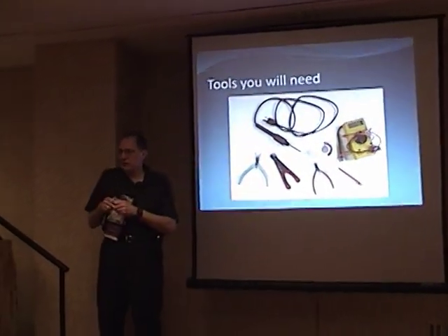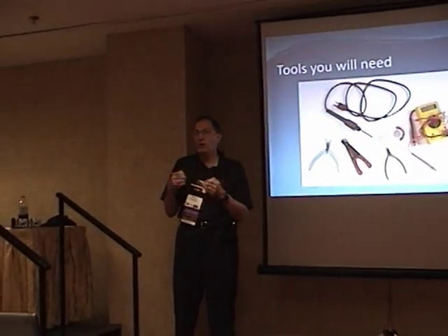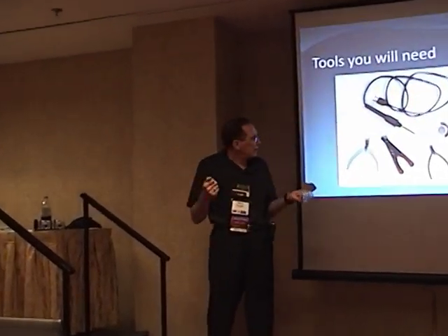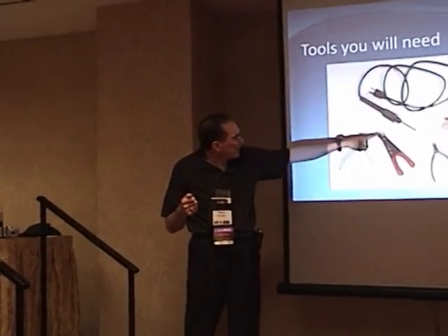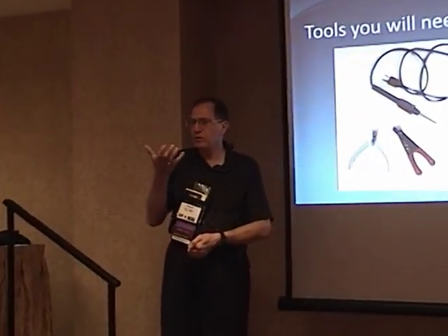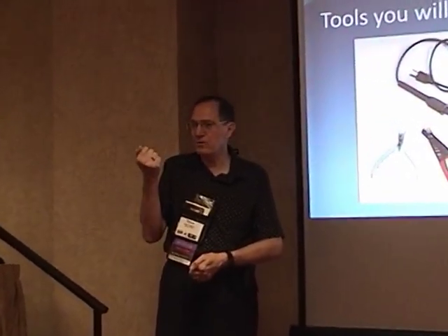You take the wire you're going to strip, a longer piece, so don't worry about it, and you move that set screw, which controls how wide these jaws open. You keep moving it until you can close it without cutting the wire in half. When you've done that, you just put it around the wire and pull on it and it strips it. So even though you're stripping a sub-millimeter wire, you can do it reliably and repeatedly if you have a little patience and buy a decent quality wire stripper. From there on out, this is really pretty simple to do.